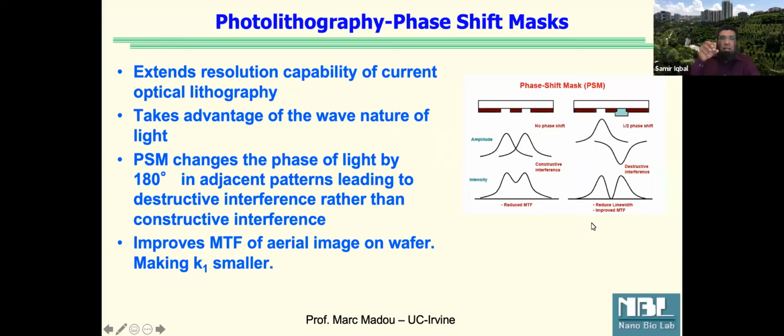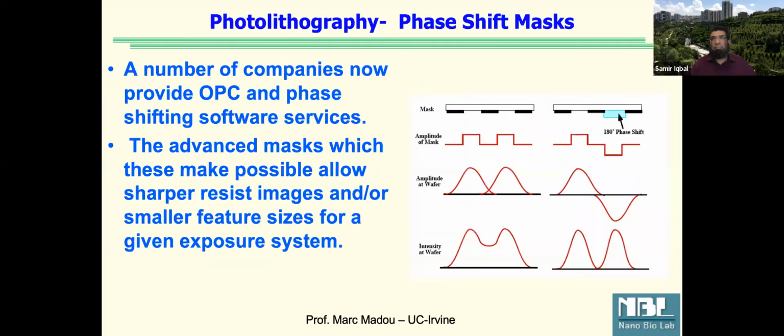So the light results in exposure of the photoresist material with a very sharp feature. So far with me? I know it's lots of visualization, and I'm hoping that I can help you visualize what's happening here. Those phase shift masks basically change the phase of light from one opening on a mask to the next opening. Hence, those two features can be translated much more effectively, right?